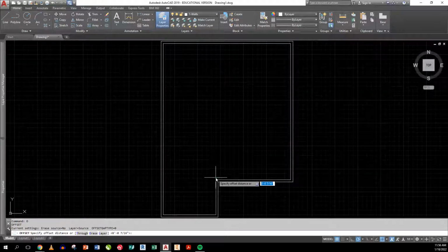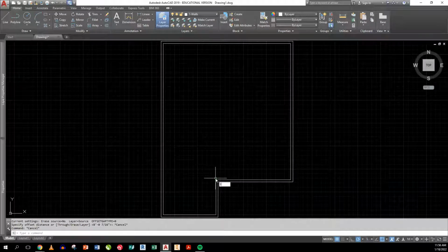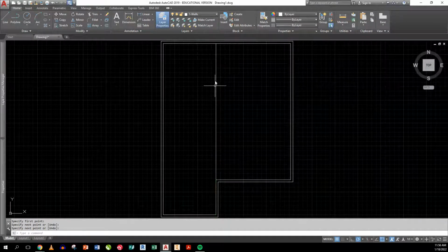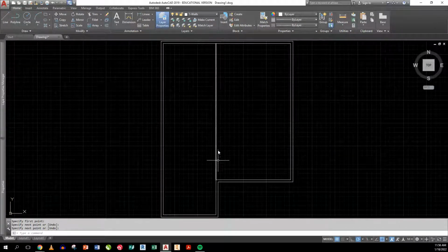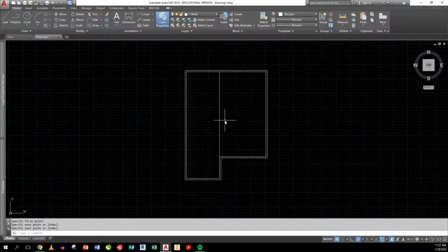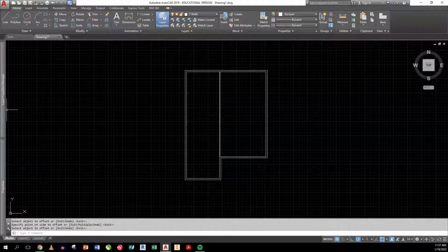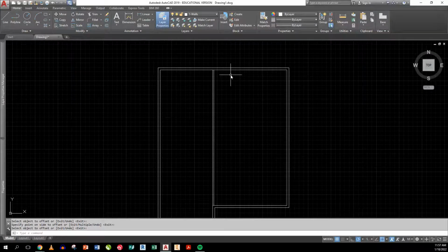Now, in this house plan, I know that I have a line or a wall that runs straight through the house like that, all the way through. It goes right from that inner wall's corner all the way through the house to the back end. Now, that wall, because it is not a bearing wall, offset, is only 3.5 inches thick. Okay? Now, this is where we start to get into some things. How big is that going to make this? Well, let's start with what we can know.